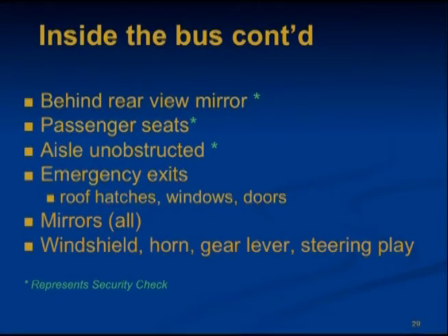Play should not exceed 10 degrees, which is about 2 inches on the 20-inch steering wheel. Steering wheel play for power steering equipped buses is checked from inside the bus with the engine running. Steering play should not exceed 10 degrees, which is about 2 inches on a 20-inch steering wheel, before the front left wheel barely moves. Check that while looking at the crossover mirrors.